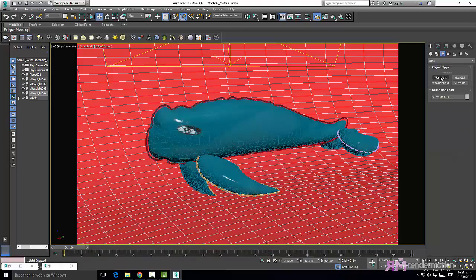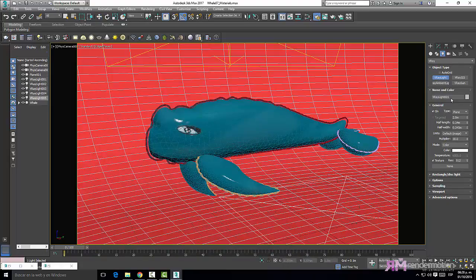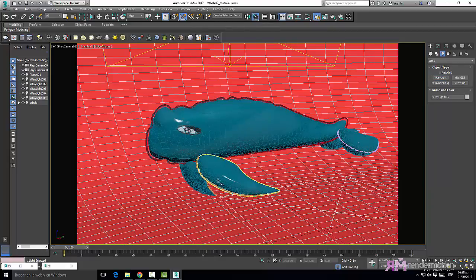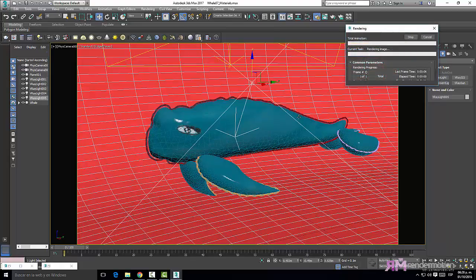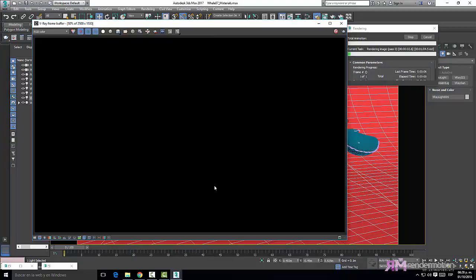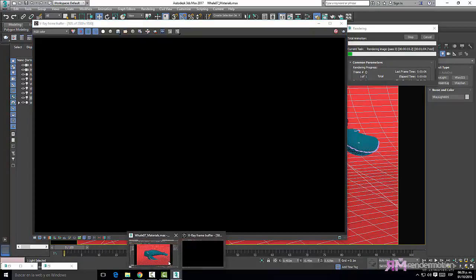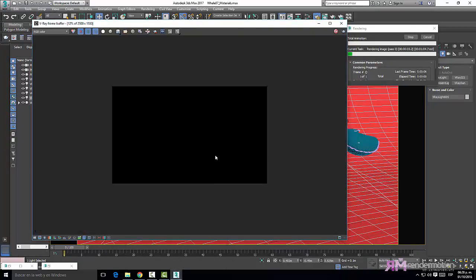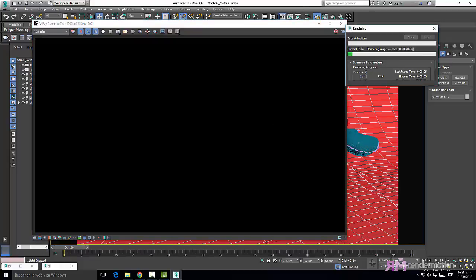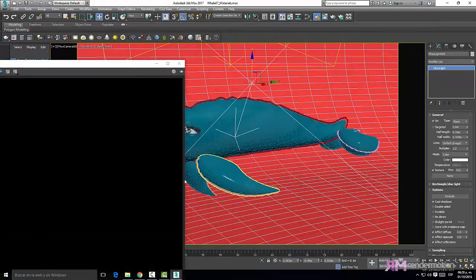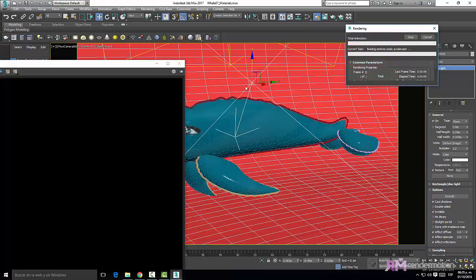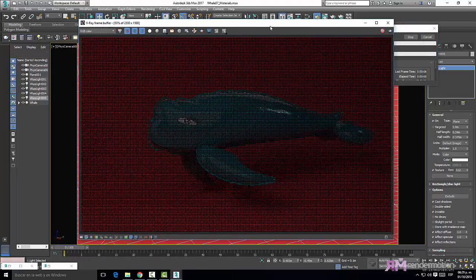Okay, I will create another V-Ray light, a big V-Ray light, with a multiplier of 1. That's what I'm liking about reflections. I will put it here. Look, now I can render, and I can see the effect of the reflection. I'm not seeing anything because the light is covering the scene. I need to make it invisible so I can see through the light. Right now it was blocking my vision.